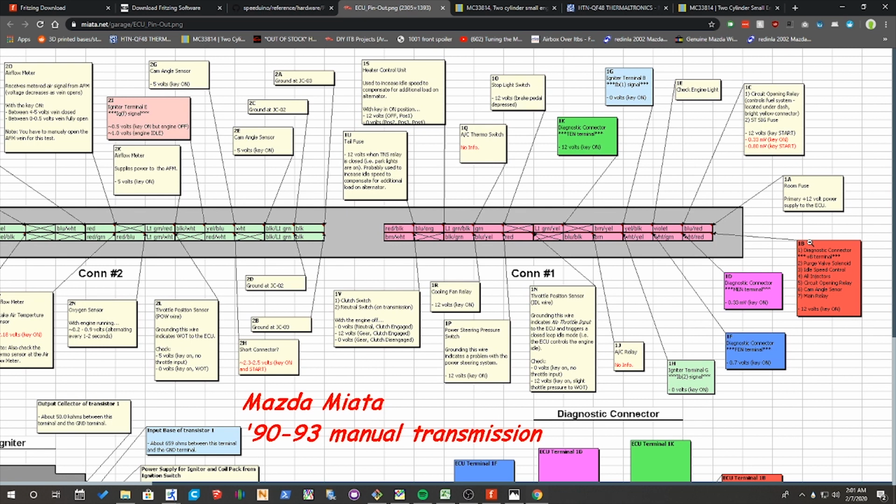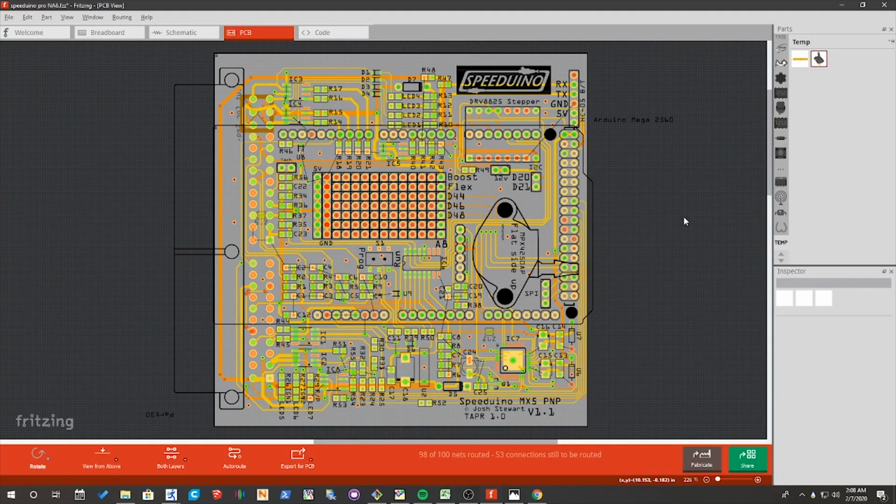At this point, I wasn't 100% sure what the voltage regulator circuit in the ECU was, but I was able to use some Googling and the program that I'm about to show you called Fritzing to figure out that 1B, our switched 12 volt power, actually goes directly to an integrated circuit on our ECU that is then turned into 5 volts. So, we know our ECU is receiving constant 12 volt power, and we know it's receiving switched 12 volt power. We just don't know why that switched 12 volt power isn't able to power our ECU.